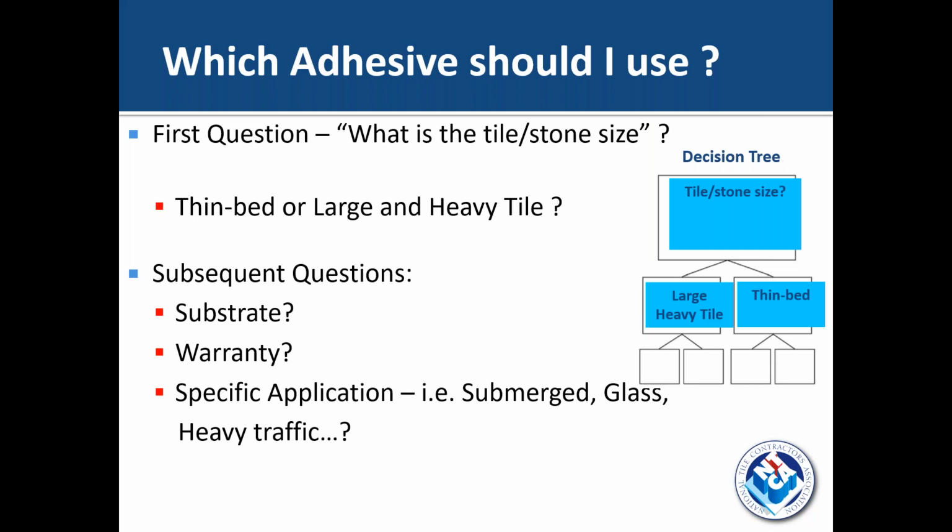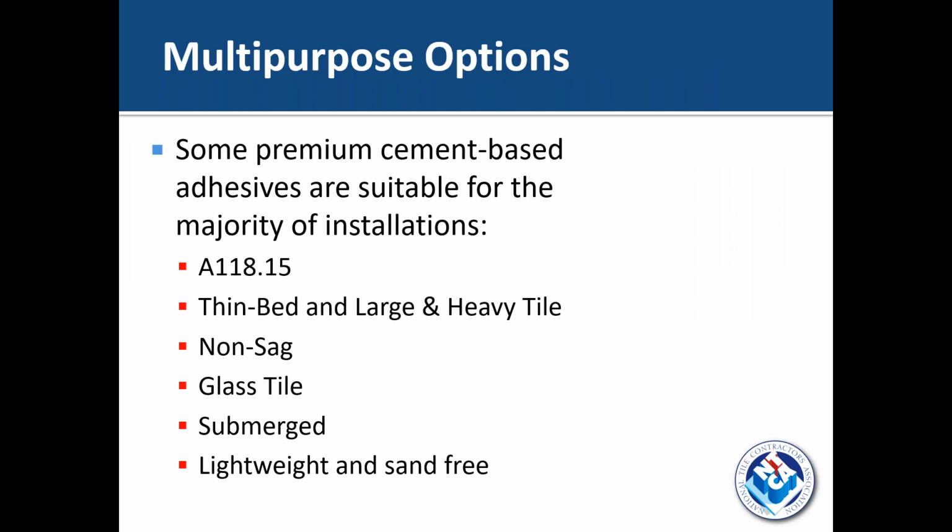But that's kind of the progression that I would suggest in terms of making your decision about which adhesive to use. And bear in mind that many of the large and heavy tile mortars, and the newer ones, can also be used for thin bed applications. So you wouldn't want to use a thin bed mortar for a large and heavy tile application, but most large and heavy tile mortars can also be used as a thin bed. Another observation is that most premium large and heavy tile mortars are suitable for the majority of most any installation.